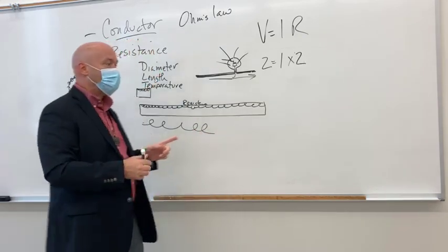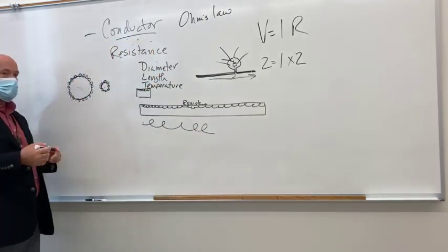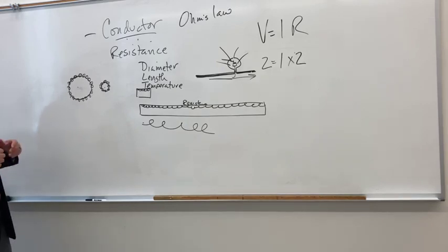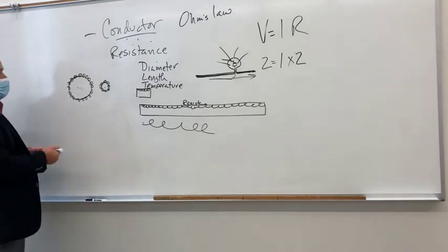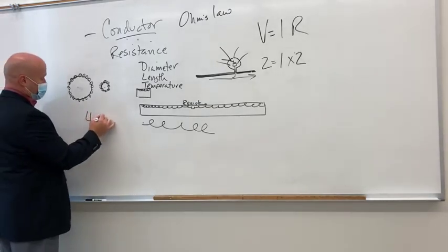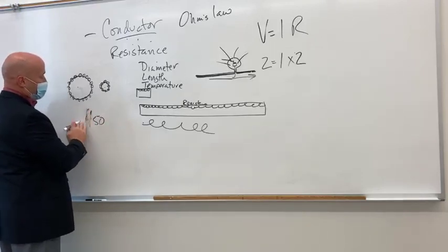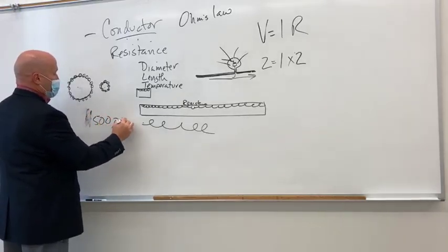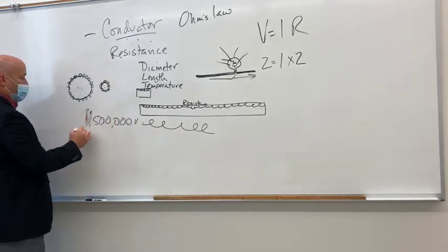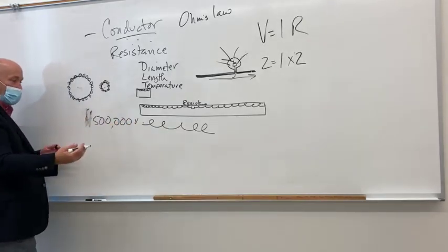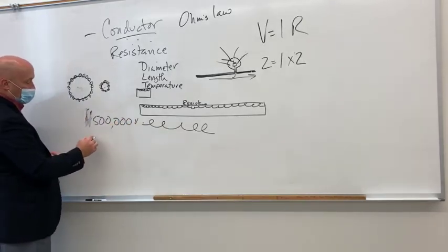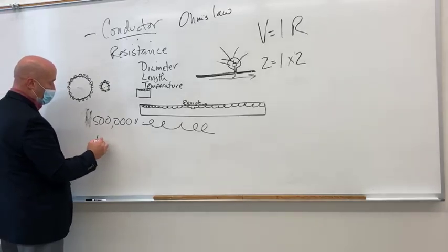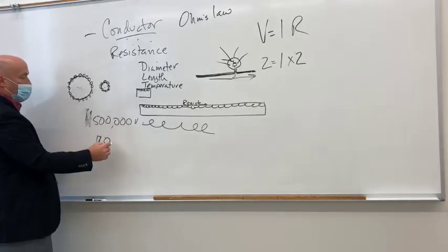So the reason electricity comes to you in very high voltage is because it's more efficient to send 400, say 450, maybe 500,000 volts at very low amperage down the electric wires than to send, you know, you might use 110 volts, 120 volts in your house.